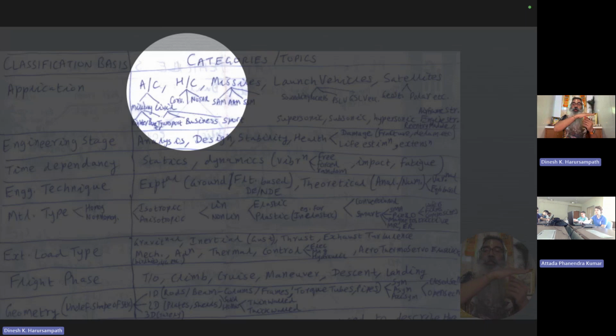And in some of these locations, there were damages in the composite, which eventually made the tail rotor fail, and therefore the anti-torque was no more active, and the helicopter had to crash. So they wanted what is known as a real-time health monitoring system, so that the pilot can know the status of not only the tail rotor but also the main rotor, all the primary load-bearing structures, so that if there is an issue with it, the pilot can make an emergency landing at the nearest spot that is available.